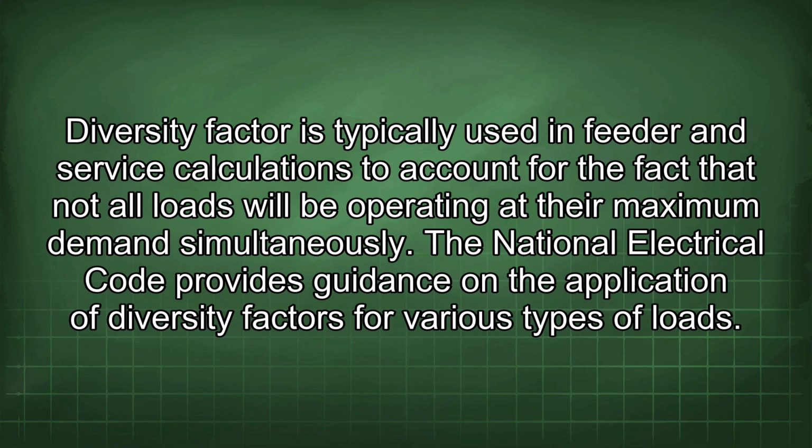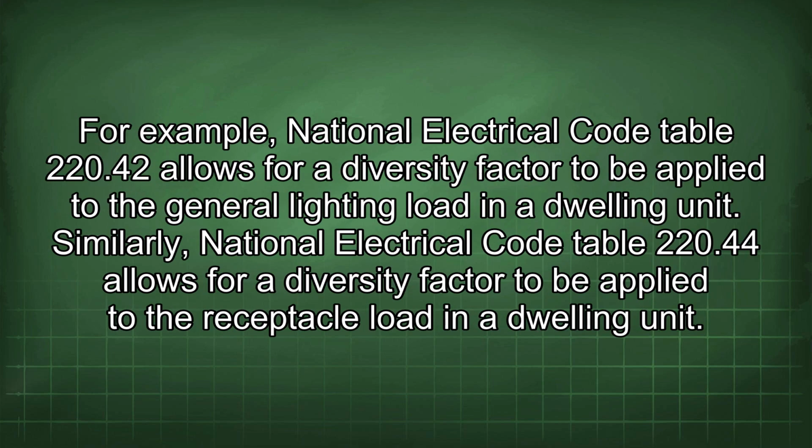The National Electrical Code provides guidance on the application of diversity factors for various types of loads. For example, National Electrical Code Table 220.42 allows for a diversity factor to be applied to the general lighting load in a dwelling unit. Similarly, National Electrical Code Table 220.44 allows for a diversity factor to be applied to the receptacle load in a dwelling unit.